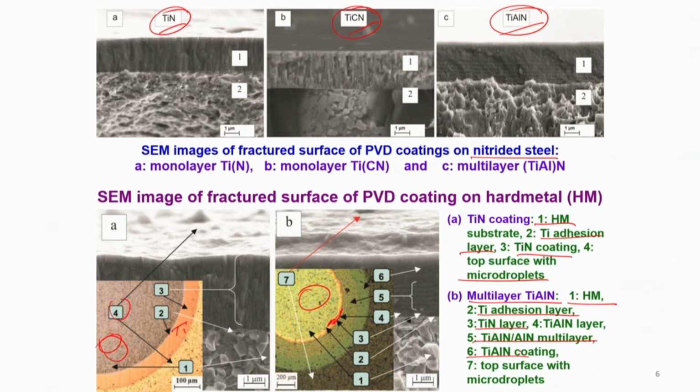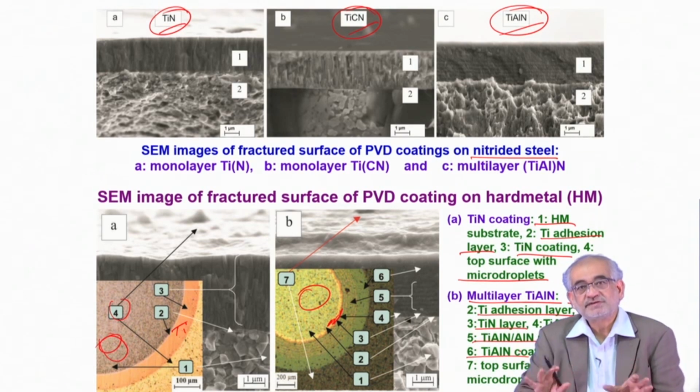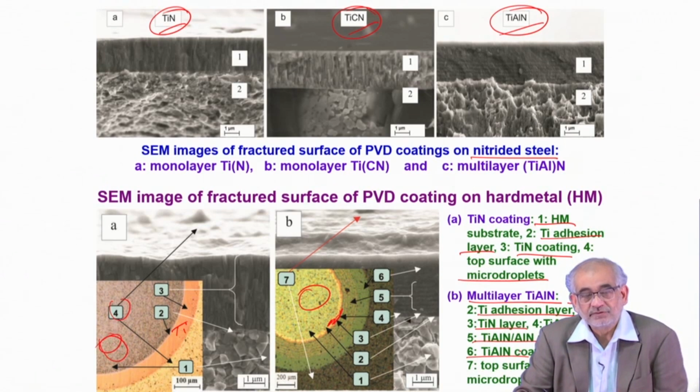The point I am trying to make is that in the same chamber, without breaking the vacuum, without moving, without needing the sample to be taken out, you can make multiple coatings. Now, in all these cases, there is one point which I haven't mentioned but would now like to stress upon, is the fact that whenever you are creating these kinds of vapor deposited coatings, maybe they are very thin films, yet the substrate coating interface is very sharp.